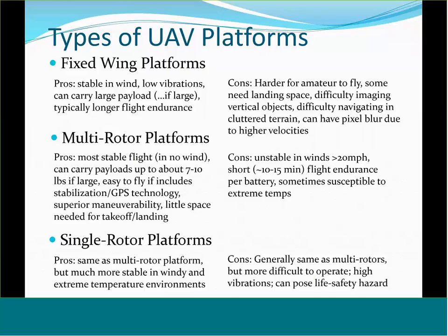The final platform are the single rotor platforms. The pros for these is that they have pretty much the same maneuverability as a multi-rotor platform, but they tend to be much more stable in windy environments due to their higher polar moment of inertia, and they tend to also perform better in extreme temperature environments.